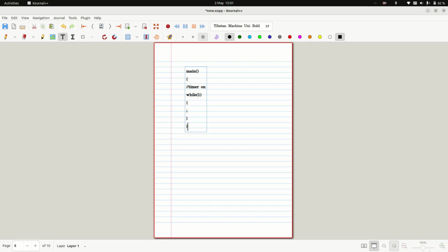So what is the total time it takes to get the INT generated? So 256 into 200 nanosecond. That is how much? 51.2 microsecond. So after 51.2 microsecond, an INT is generated.